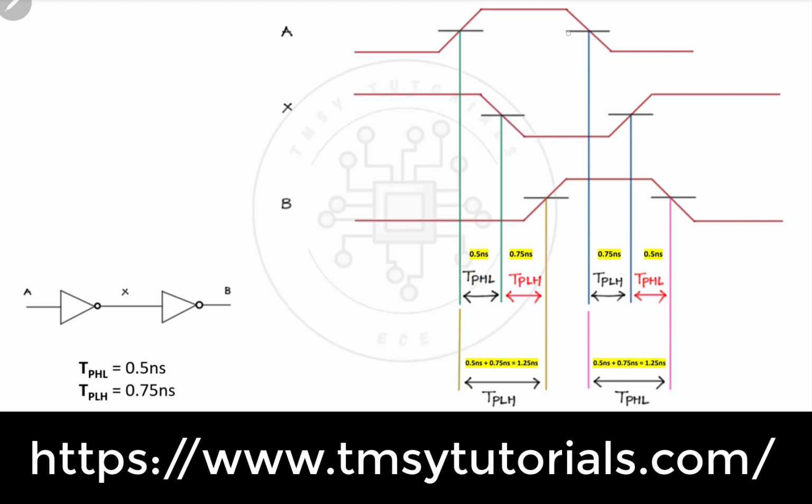Similarly check at this point. For the 50% point, draw a vertical line, and here at the 50% point, draw a vertical line. So this is nothing but TP-LH, and it should always be written with respect to the output. Here the output is X, which is moving from low to high. That's why here I am writing TP-LH. Now we are done between A and X.